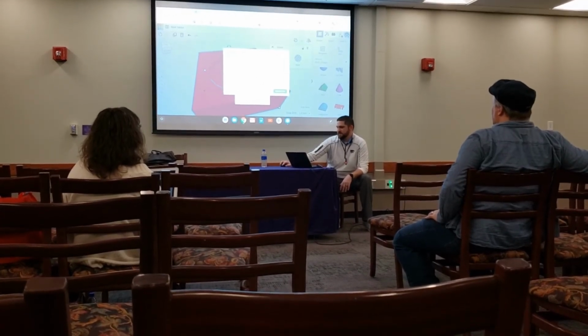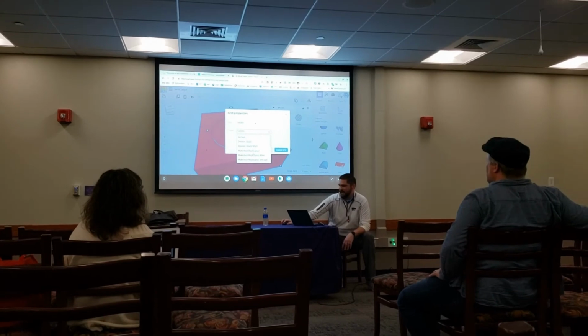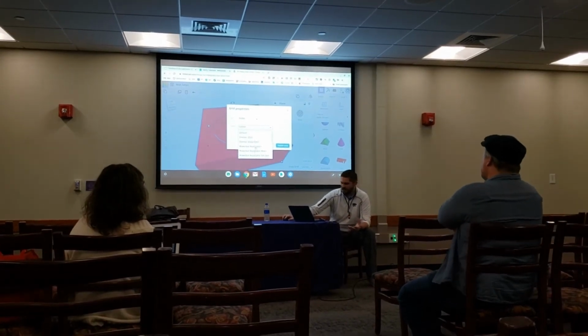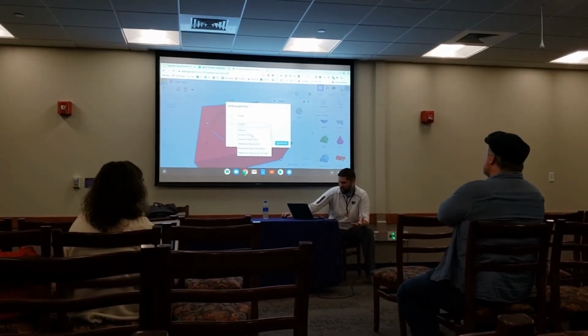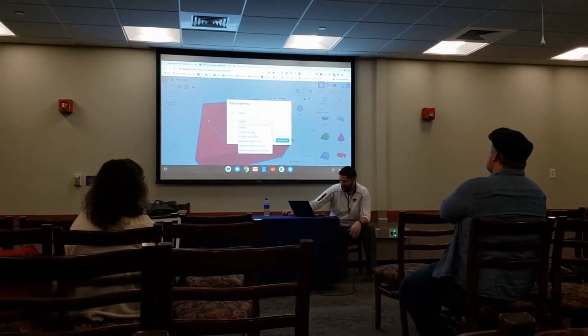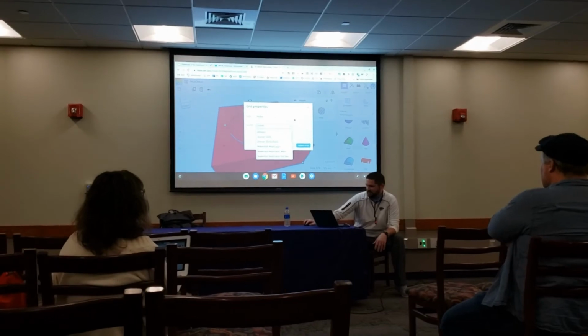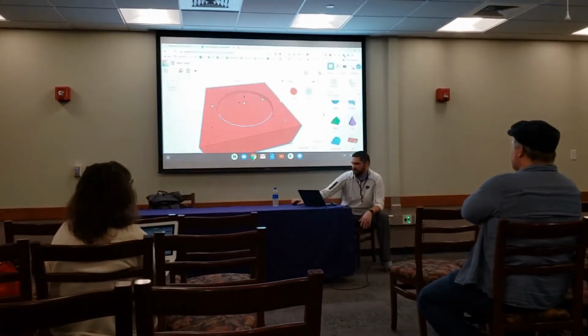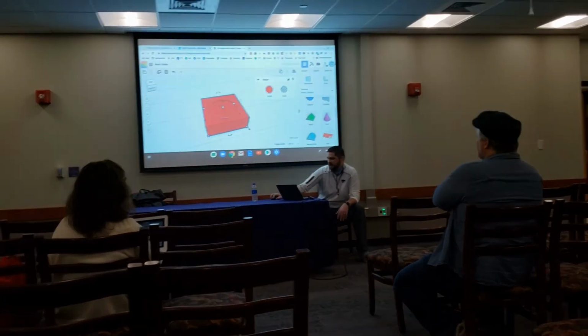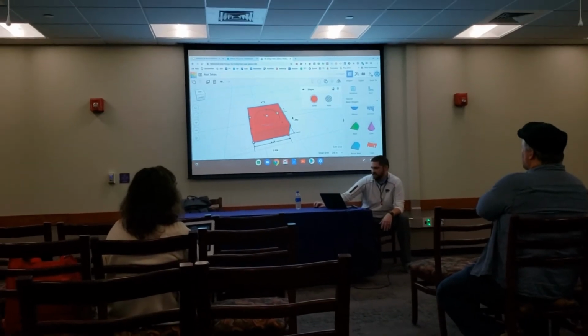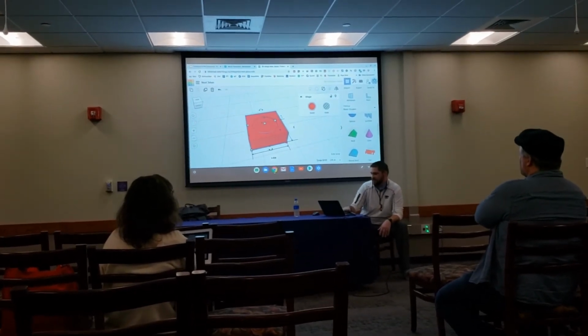There are specific 3D printers whose companies work directly with Autodesk and Tinkercad, and you can use that, but unless you have one of those 3D printers, it's not real helpful. But that will update the grid, and so now when I resize objects, I'm resizing in inches. If I want this to be 1.5 inches, I've got to put in 1.5.